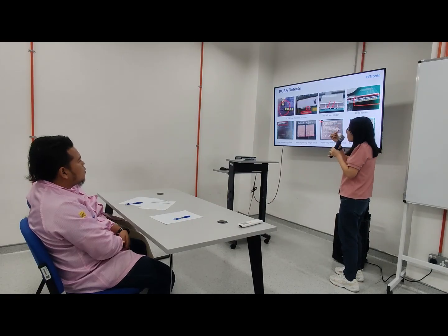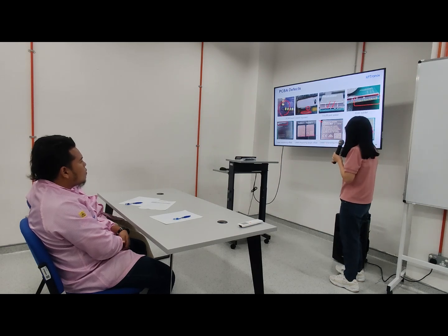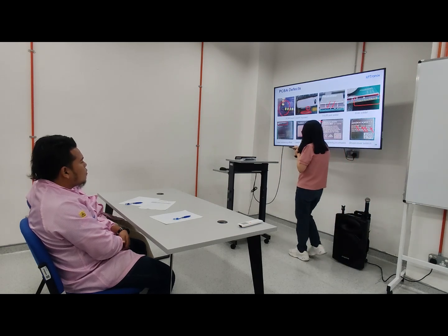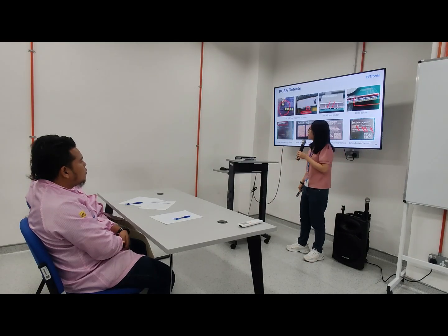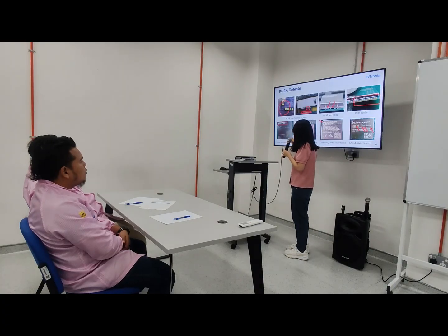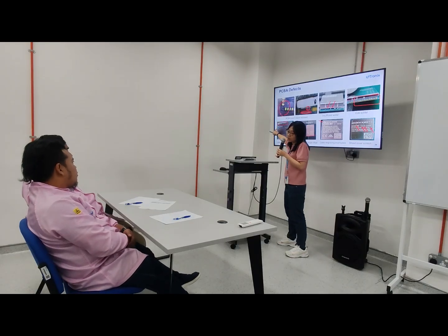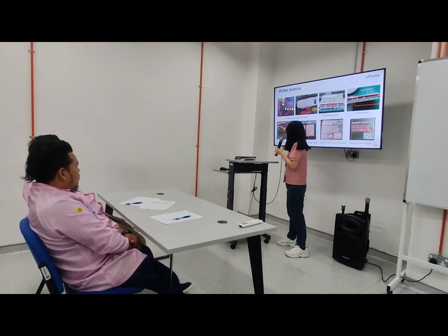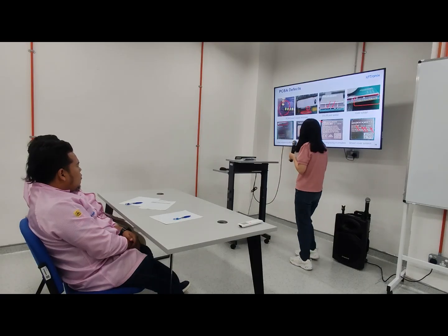Cold solder, it didn't melt, it is just round like that, it didn't melt properly. Cold solder. Next is laser engraving set. What's the issue of this one? Q1. Yes, actually it's already offset, just moved upwards. And this Q wording also didn't update. All the wording also went to the upper level, shifted.